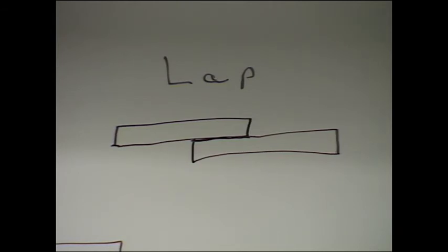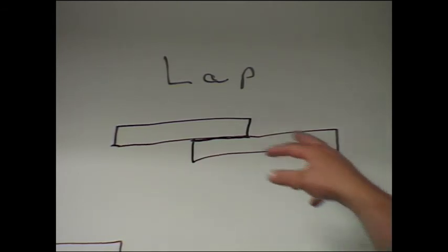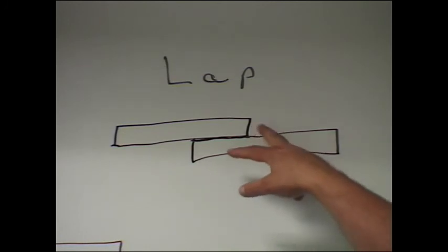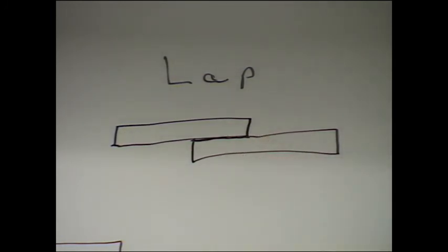And that will also prevent it, because if you only weld on this side, the weld is going to start shrinking, and it'll start actually pulling it apart on the back side. So if you can weld it on both sides, that'll give you maximum strength, and that's the most desired, but in a lot of applications you might not be able to do that.